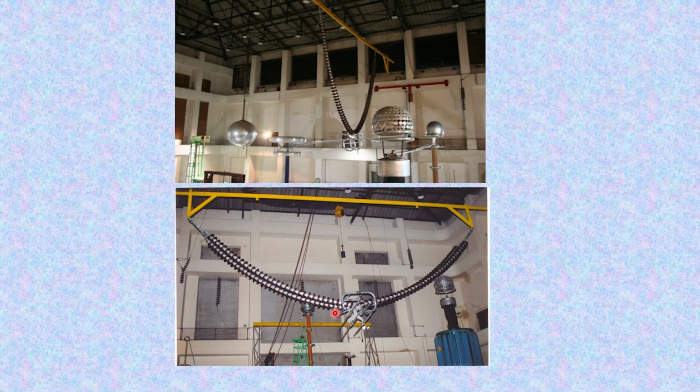So, what happens in case failures are observed, and how much will the stress be increased in the adjacent insulators, we will be looking at after this, in the tests which are being shown here. We will see how the performance of the string behaves in case there are faulty insulators in the string. A faulty insulator could be anywhere in the string. So, how the performance, the grading or the potential distribution, gets modified.